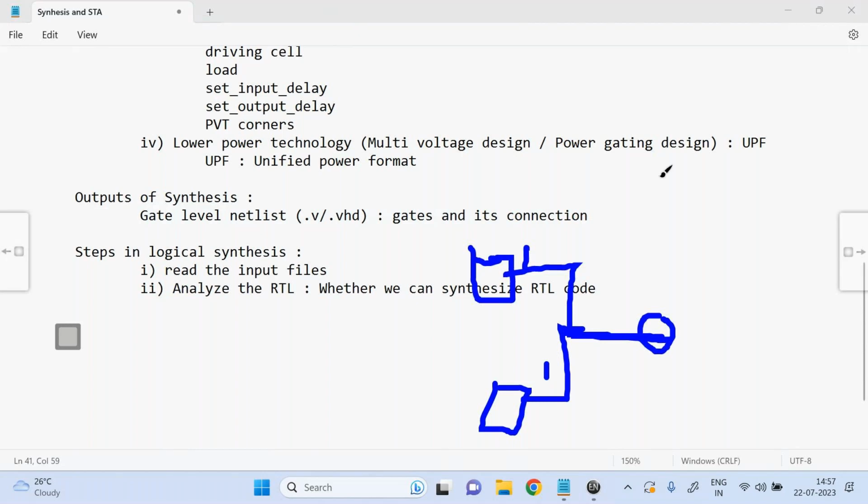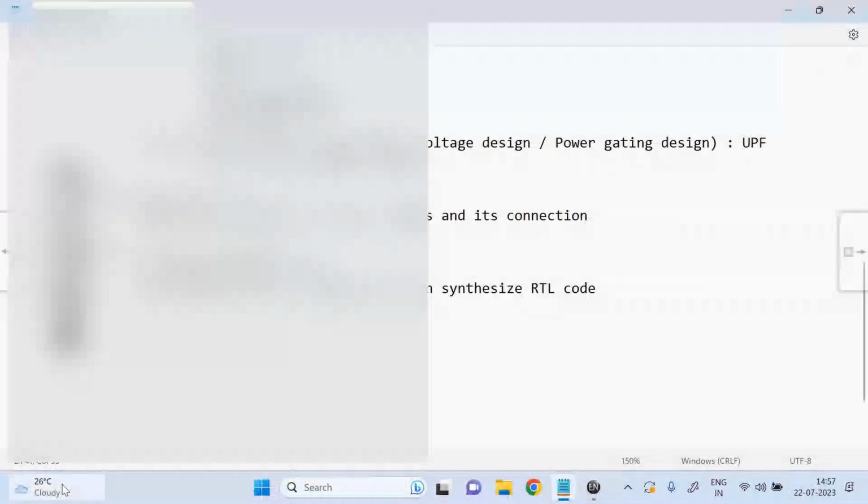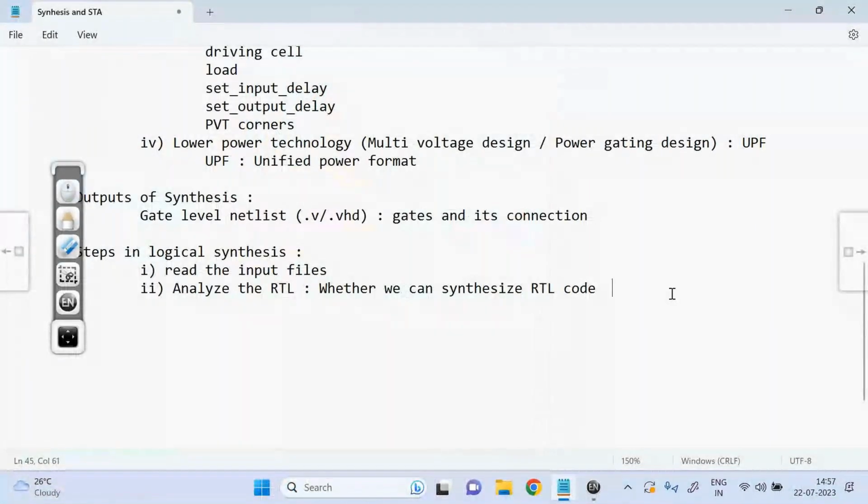So you may have some ports in the design which are not connected at all, left unconnected. Also, in the netlist you may have assign keywords. Assign keywords should not be there. In the netlist you should see only cells and their connections. Declarations like input, output, wire are fine. You should not be seeing any assign keywords. If that is there, you can report it after synthesis, and even in PD.